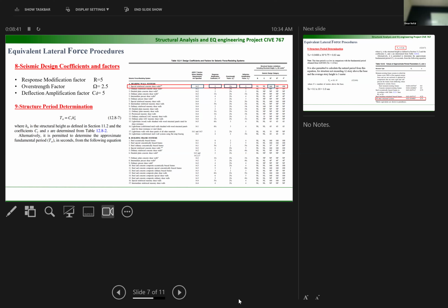Either to make the building very, very stiff, very, very strong. If it's gonna be hit by an earthquake, it's not gonna move. But if it got damaged and failed, we have big cross sections, okay? It's gonna be a disaster, okay? Or we are gonna make our building flexible. Like, okay, if the earthquake hits, I'm gonna allow some damage, but it's not gonna lead to failure.